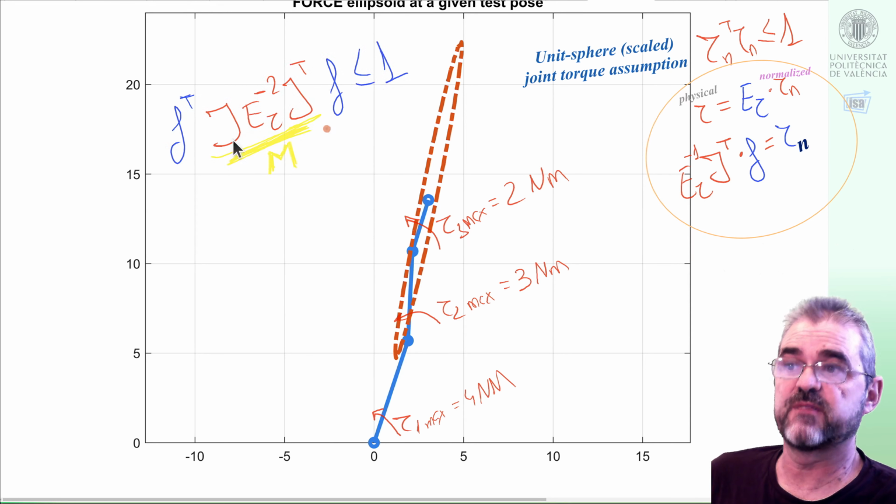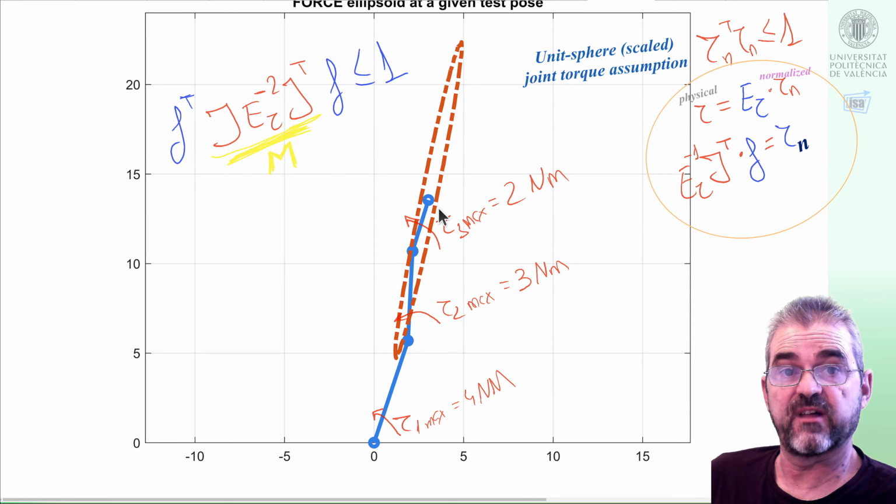So this is the force ellipsoid, and with the code you can download, I depicted it with the center at the end-effector position, just for cosmetic reasons, because the axes in this figure have meters as units, but the force has newtons as units. But superimposing everything renders a clearer picture.